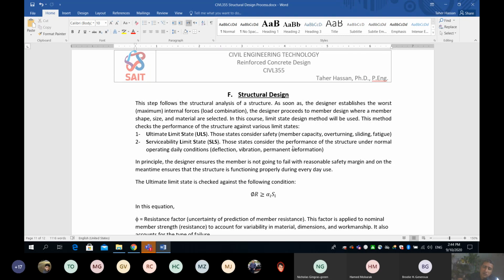some of the pipes are connected to the floor, and sometimes the pipes will crack. Anybody wants to get another 1%? What else can cause a problem if the slab or the floor deflects so much? Settlement. Typically, settlement we refer to the whole structure will go down into the soil. So I don't want to use the word settlement. I would prefer to use deflection.